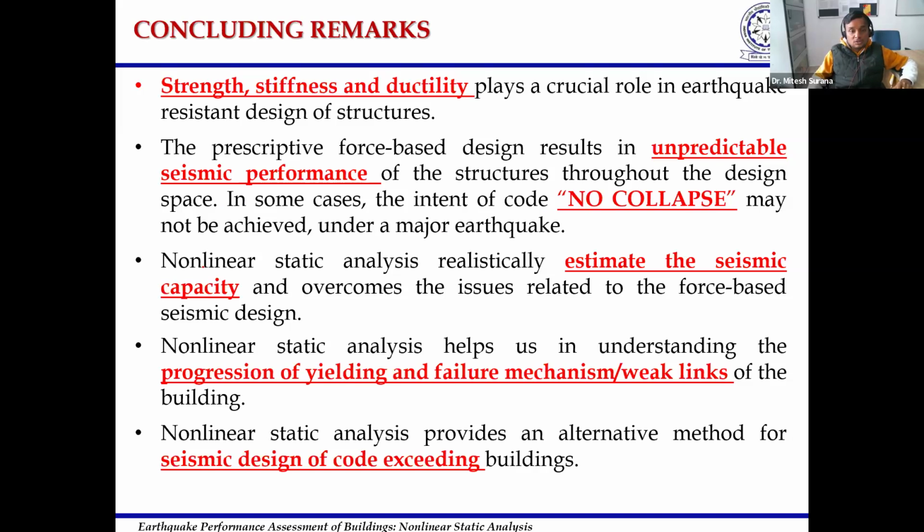So nonlinear static analysis helps us in realistically estimating the seismic capacity of the structure, and it overcomes the issues that are related to force-based seismic design. And nonlinear static analysis helps us in understanding the progression of yielding or the failure mechanism of weak links of the building. So depending on whether hinges are forming, we can identify what are the weak links and what are the strong links associated with the building.